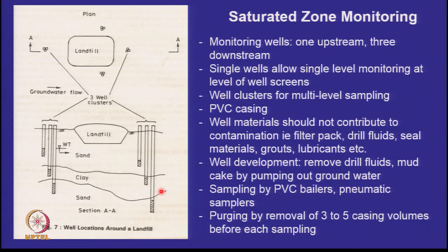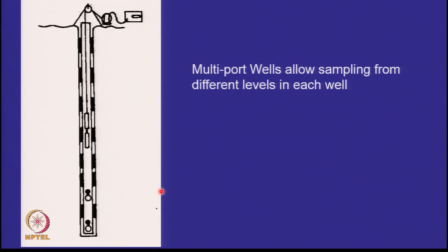And we brought about the concept of a cluster of wells, so that you are monitoring the groundwater quality at different depths on the upstream and the downstream direction. And we also became familiar with the concept of multi-port devices. That means in one well, how you can take samples from different depths.